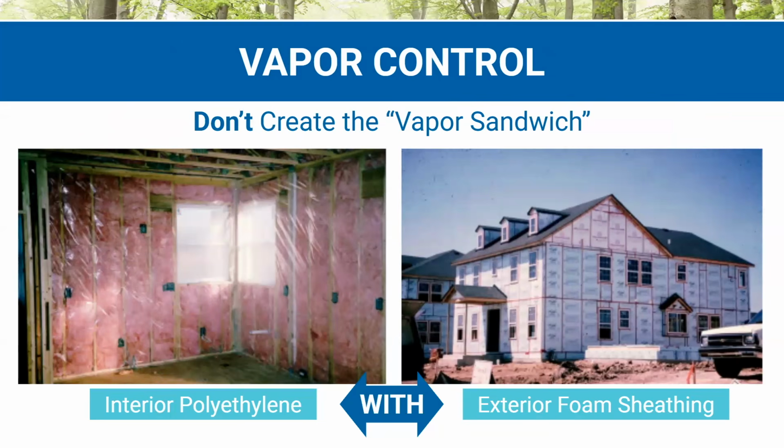And so we really never want to have 2 vapor barriers. One could make sense on the exterior side of a below grade assembly, our damp proofing or our subslab vapor barrier. But we really don't want to use poly membrane on the interior side of our walls, even in our more northern climates. And we really, really don't want to have 2 vapor barriers.